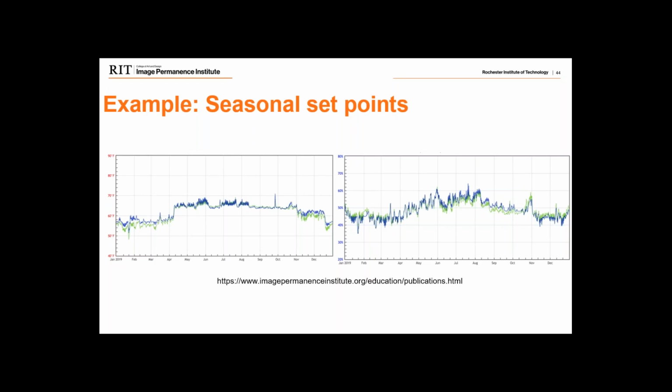And the link there will take you to our methodology, and you can download the section on seasonal set points to learn more about the benefits of doing so and how you might implement it in your own institution. But I wanted to illustrate some data here from one location. On the left is temperature and on the right is relative humidity. You can see that when we talk about seasonal set points, we're not talking about letting the temperature skyrocket up or the relative humidity go out of control. We're talking about reasonable changes from one season to the next that allow us to maximize preservation and sustainability.